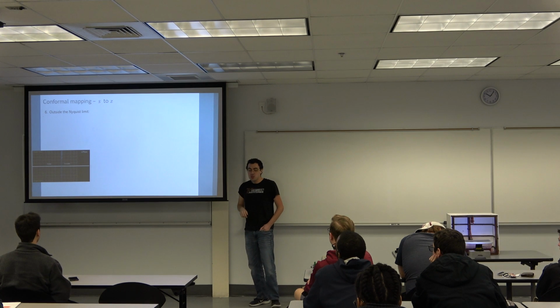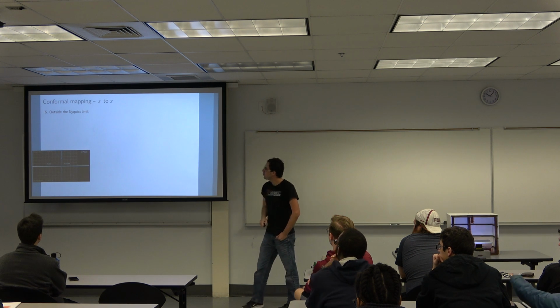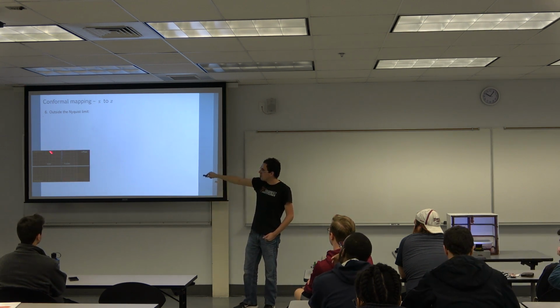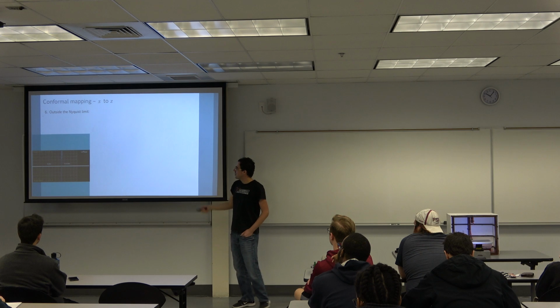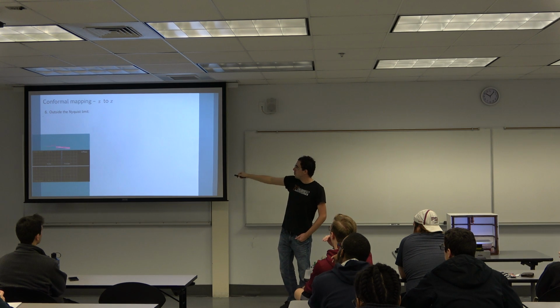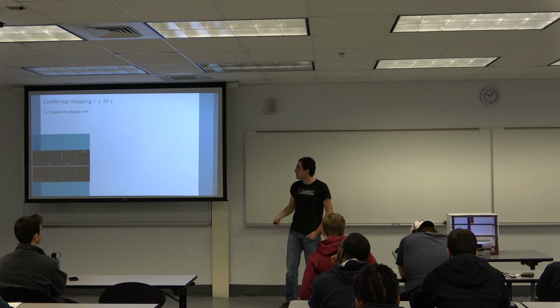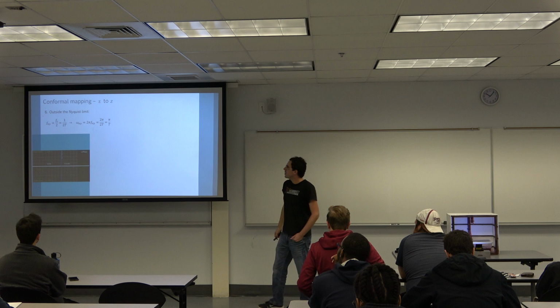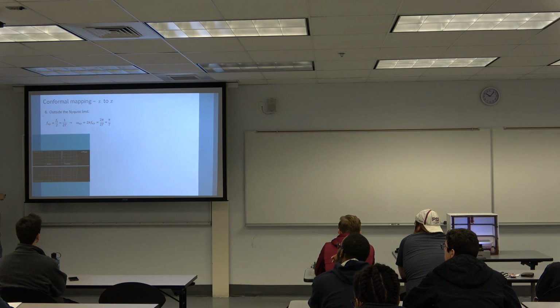Okay. So we explored pretty much all of the S-plane, except for a detail. We actually looked only between the Nyquist limits, which I'm going to claim is i pi over T plus a, and we're going to see this. So the region I'm talking about is above the Nyquist limit, where we have some frequencies that we can't resolve, as I was discussing, right? This is kind of tricky, but the Nyquist frequency is half of the sampling frequency. The sampling period is 1 over the frequency, so this means that the Nyquist frequency is 1 over 2 capital T.